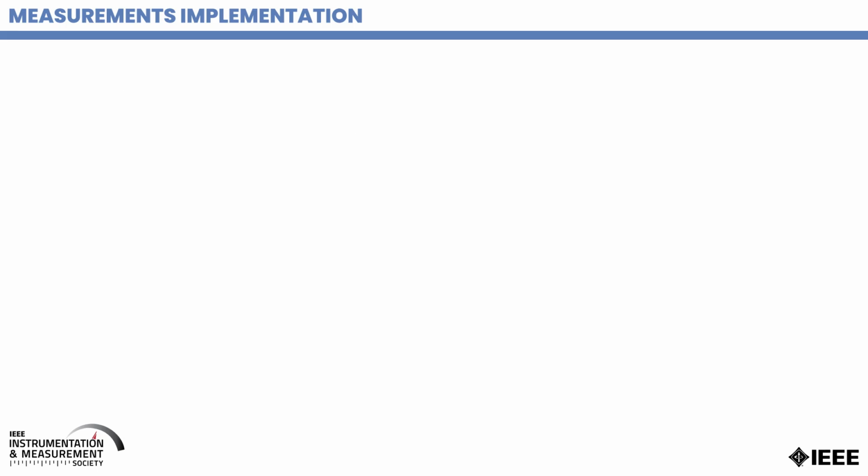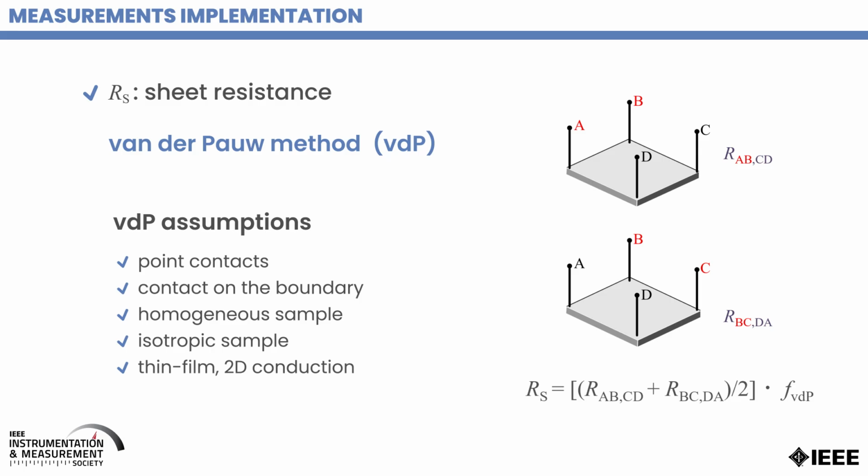measurement. On the other side, the so-called Van der Pauw method requires four contacts, but no more inside your sample, but at the boundary of your sample. And with two dual resistance measurements, four-terminal measurements, it is possible again to get a global estimation of the sample resistivity, sheet resistance in the case of thin films. You can think about electrical resistance tomography as an extension of these more established techniques.